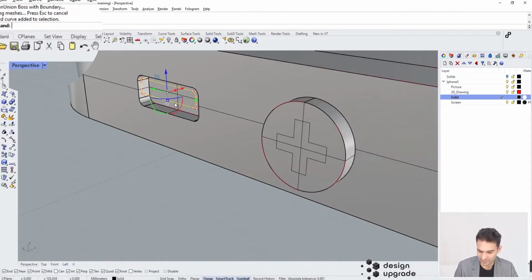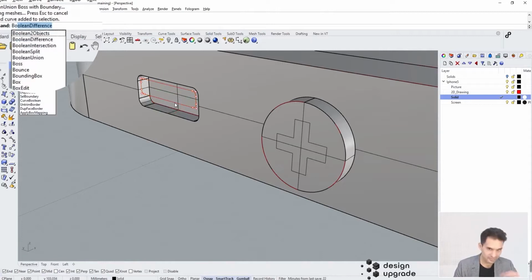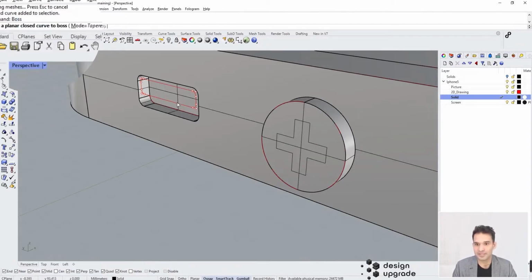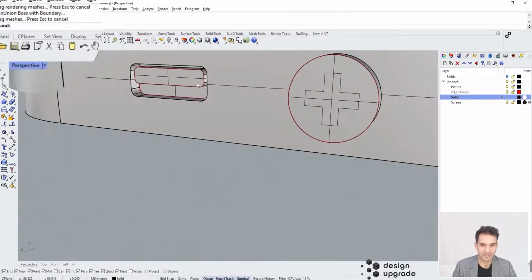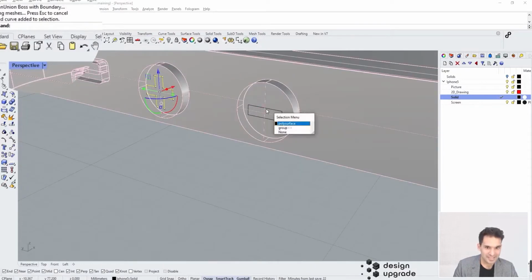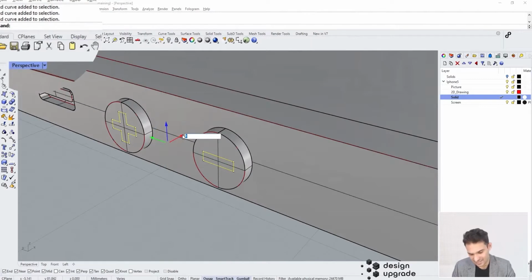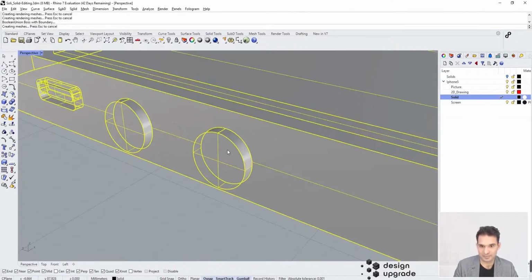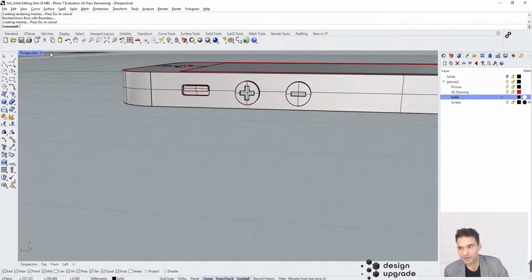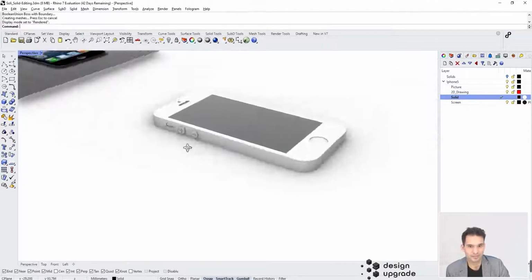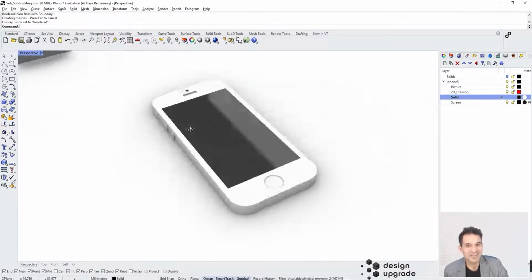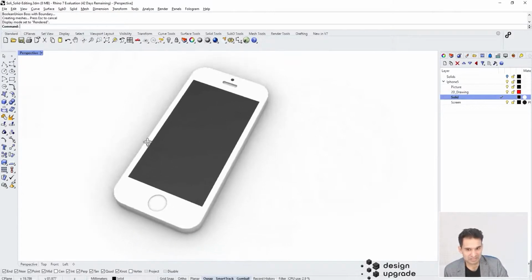Now I can just say boss again. I mean, we could leave it to the geometry and just extrude it, but let's say just boss. Let's not go crazy. Boss this guy, please, with this guy. And now we have already that detail there, that if we just take these 2 curves, this guy and this guy, we move it inside, let's say 0.5, and then we say boss. While they're still selected with this boundary, we now have this geometry. And if we look at the rendered, it looks more than beautiful. Yeah, so we already have actually a big chunk done, I would say.